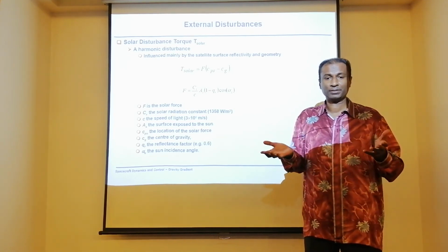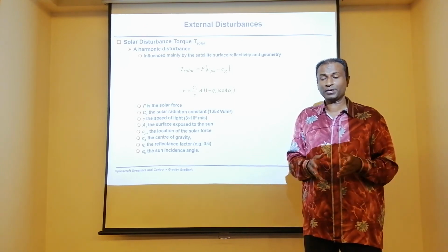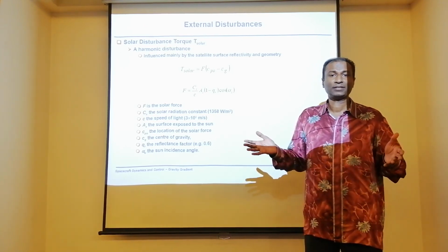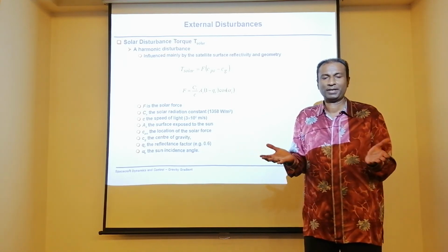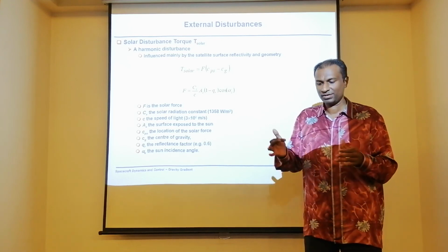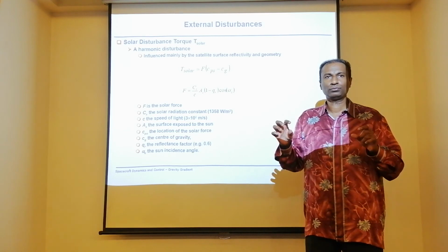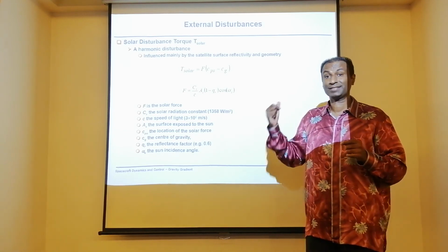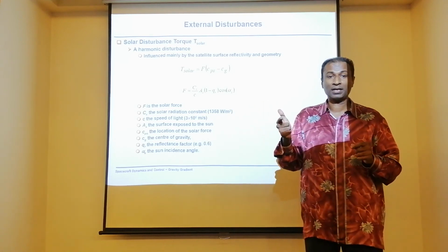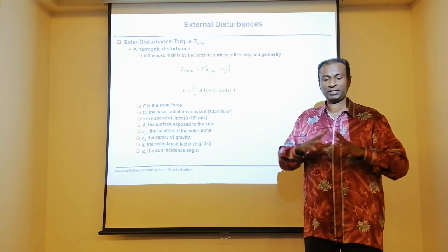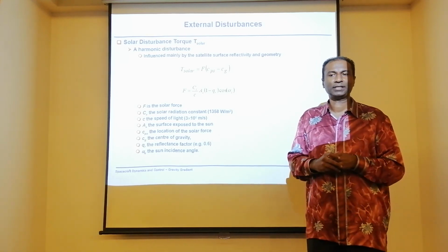Just like I've given an example, you can do it so that aerodynamic drag is not affecting your pitch. Yes, but that is not the best model. You need to make sure that you give a worst case. So the alignment of where you put the pressure point of these disturbances, especially the aerodynamic and solar, is important so that we can design for a worst case scenario. So we'll try that in an exercise. Thank you.